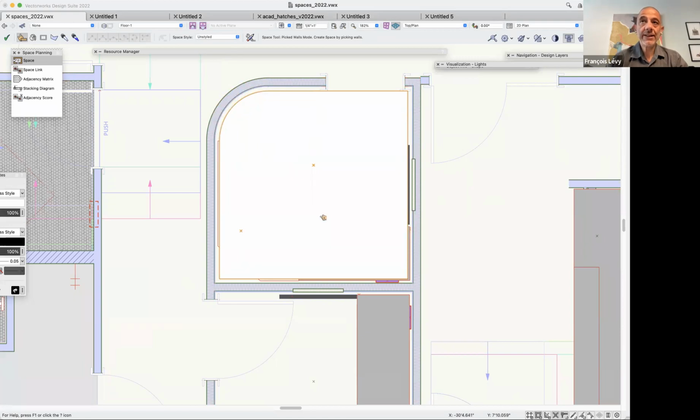So for example, I typically include a base component for my wall styles. And while that baseboard is only 3.5 to 5.5, whatever inches tall, Vectorworks reads it as a space component. So if I use this methodology in order to create space objects, I just need to be aware that it's going to make the room seemingly 3/4 of an inch or an inch and a half smaller all the way around. So that's one thing to think about.